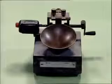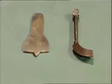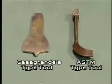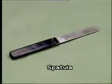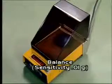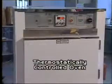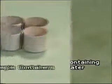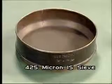The apparatus required for conducting this practical include mechanical liquid limit device, grooving tools like Casagrande type and ASTM type tool, porcelain evaporating dish, spatula, balance with sensitivity to decimal 0.1 gram, thermostatically controlled oven, wash bottle containing distilled water, sample containers and 425 micron IS sieve.